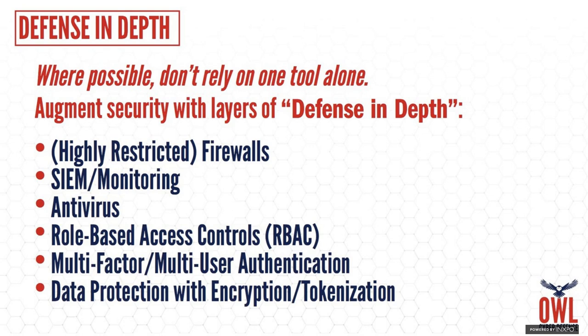Sure. So I assume Corey's asking in a two-way solution, probably not in a one-way solution. Probably that third scenario. Oh, one-way, is this one-way out? So if it's one-way out, let me just describe a little bit more detail about the data diode. The data diode on the source side has an LED basically that's sending light.